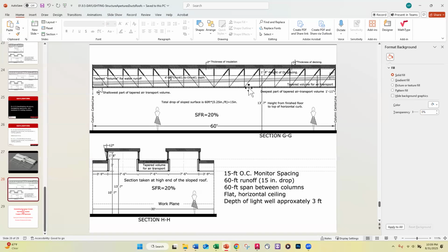You could make that hung ceiling tiles, in which case you'd have 1.5 deep aluminum T's supporting the acoustic panels, and then those aluminum T's would be hung off of the corrugated decking. All that really needs to be worked out in the end. And by the way, your engineer won't do that for you. You're the architect, and you need to think about what those finishes are.